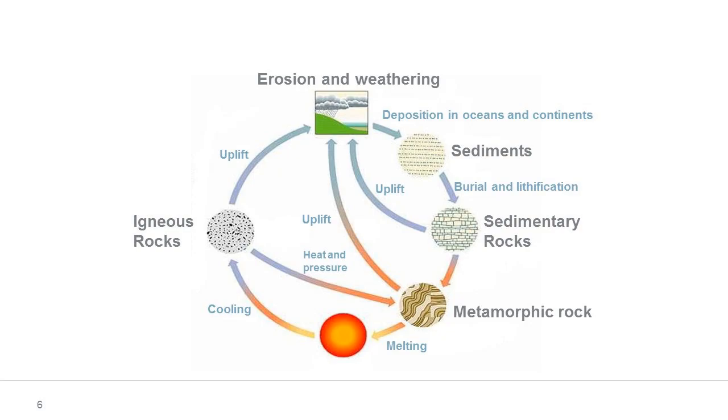Stone is a natural quarry product and will vary from tile to tile even when mined from the same quarry. It can have a tendency for warping, staining, or discoloration, and this will also vary within a typical supply. With this in mind, we will take you through the key watch points by providing you with a basic understanding of the types of natural stone tiles available, the considerations when specifying the mortar, grout, and installation requirements.